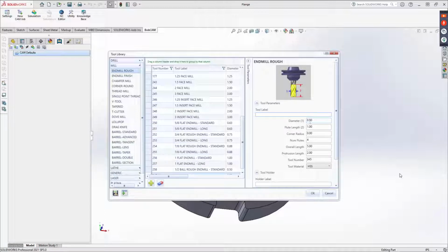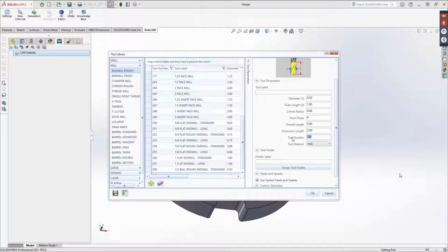It just means that we're going to automatically generate one. So what happens sometimes is it may change tool numbers on you because you think that it's the tool that you wanted to define, but really it just created a new one based off of what you've entered to define one that works for the cut. So they may not get the tool numbers you want. So I don't really worry too much about tool numbering at all until the end of the program.